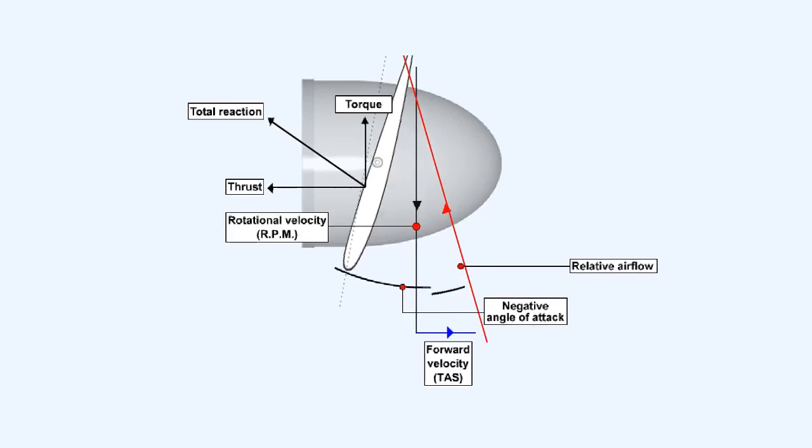Propellers which can have their pitch angle made even more negative are known as fully reversing propellers. As the power lever is moved further rearwards into the reverse pitch range, the blades move into the negative pitch position. The reversed total reaction produced now increases. This exerts increased load on the engine, so engine power is increased in order to maintain a constant RPM. The engine power and reverse airflow through the propeller is now being used to slow the aircraft down. This condition is known as power-on braking.